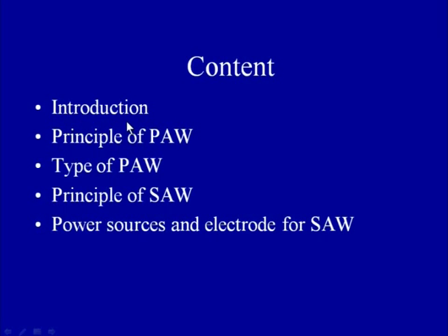As far as the content of this presentation is concerned, we will be looking into the aspects related to the plasma arc welding process and submerged arc welding process, then the principle which is used for generating the heat in the plasma arc welding process, and this heat is then used for melting the faying surfaces to develop the weld joints. And depending upon the way by which the arc is generated and the plasma is formed for the welding purpose, we can have either transferred plasma or non-transferred plasma. So, accordingly we will look into the two common types of the plasma arc welding process.